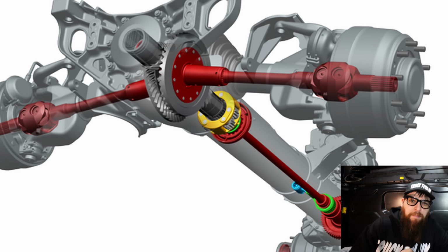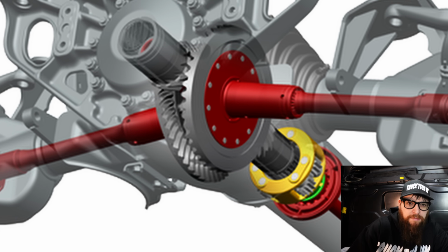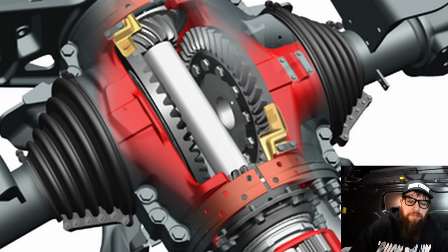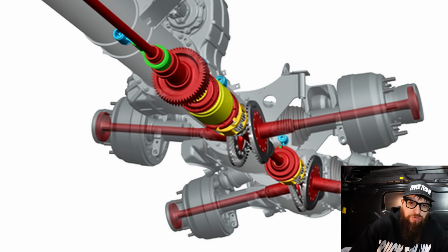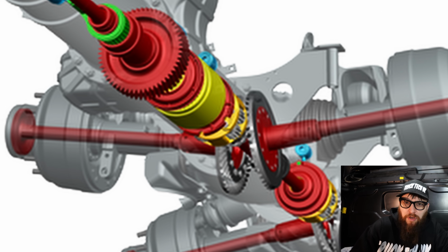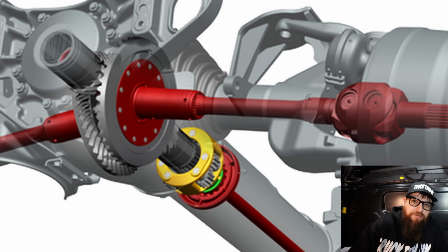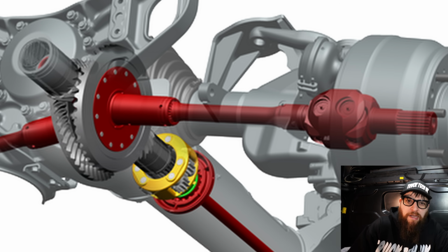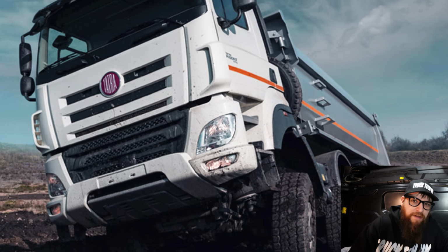Tatra's axles are a pair of driven crown wheels, one per half axle, left and right, and a pair of pinions transmitting the torque. The differential is placed outside the axle in the central load carrying tube, and unlike the classic axle solutions with a bevel differential, this is a so-called cylinder type differential, so the inner space of the housing is adapted for the swinging motion of the half axles, or crown wheels. All very complicated and very slick.